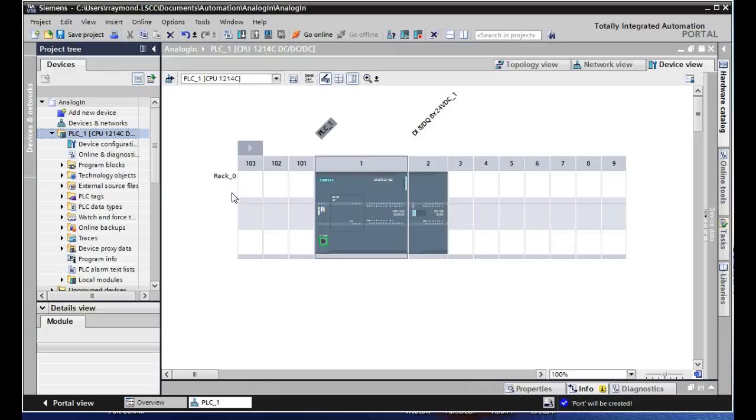Okay, the fraction of 10. So we'll start off. What we see is a count, but that count actually equals around 10 millivolts per count, right? So I just did it mathematically, but inside the PLC, it seems like they should have an instruction to actually do that. So Siemens supports an instruction called normalize that allows us to take it in one unit and convert it over to another, which is really, really slick, guys.